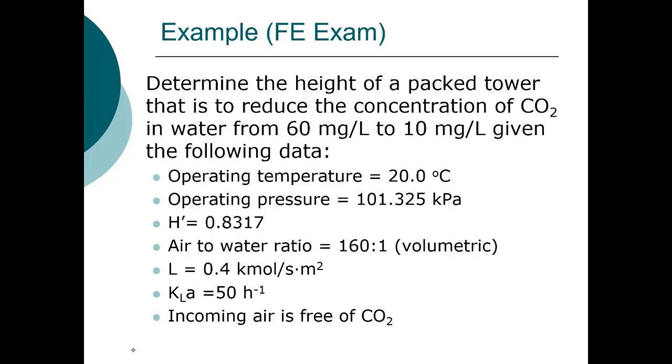the removal of CO2 requires significant chemical addition. It also results in production of sludge, and that gets us nothing in terms of hardness removal, but it costs us in terms of chemicals and it costs us in terms of sludge disposal. So we want to find a way to remove that or to reduce the concentration of CO2 so we can reduce both chemical addition and sludge production.